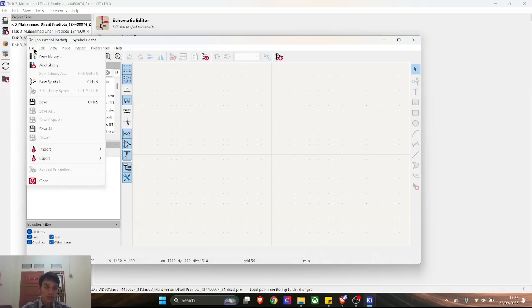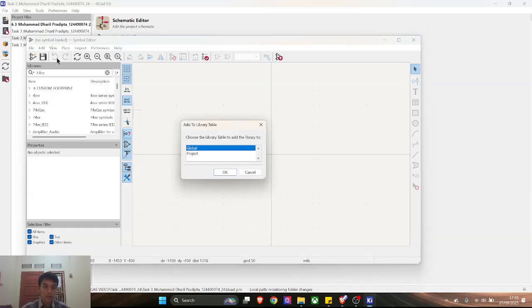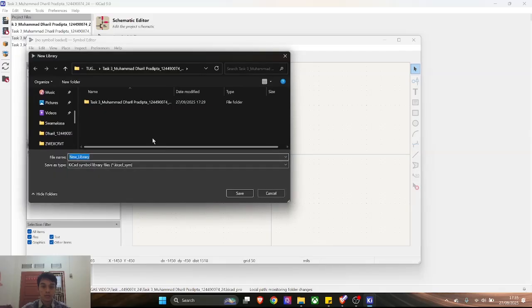So let's create a new library by clicking File, New Library, and select Global. So it will apply to all projects. If it were for this project only, just select the project. For this video, I will select this project only. So let's press OK. Then we'll put this into the same folder as the test project.